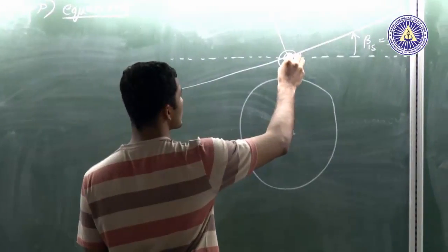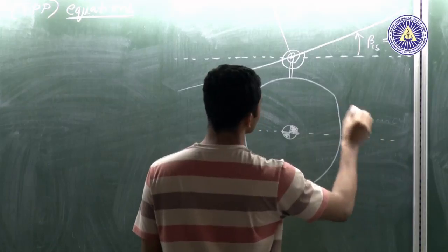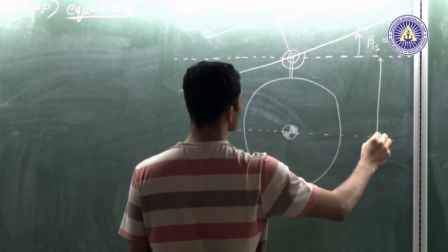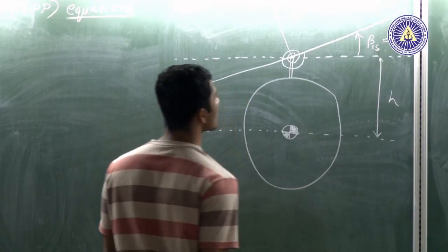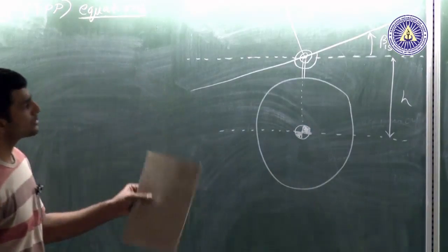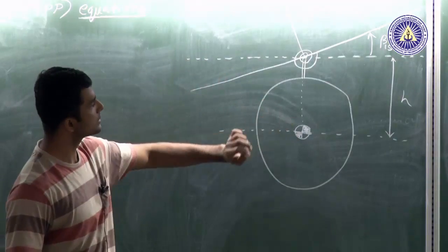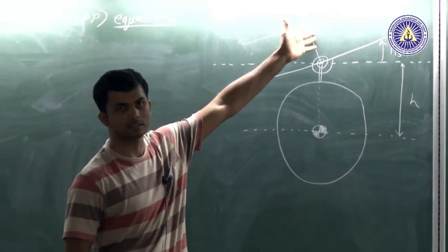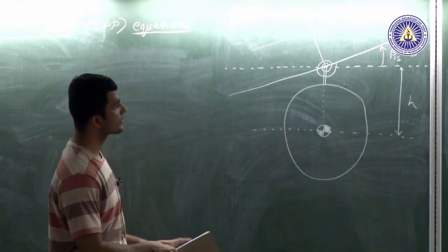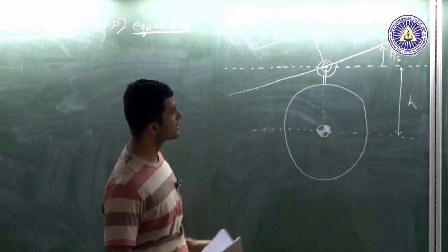and the distance of the center of mass to the hub is h. Because of this, there are two sources of moment because of this rotor on this fuselage. One is due to the tilting of the thrust vector and the other one is due to the spring, because of the deflection of this thing. So there will be another moment acting on the fuselage.